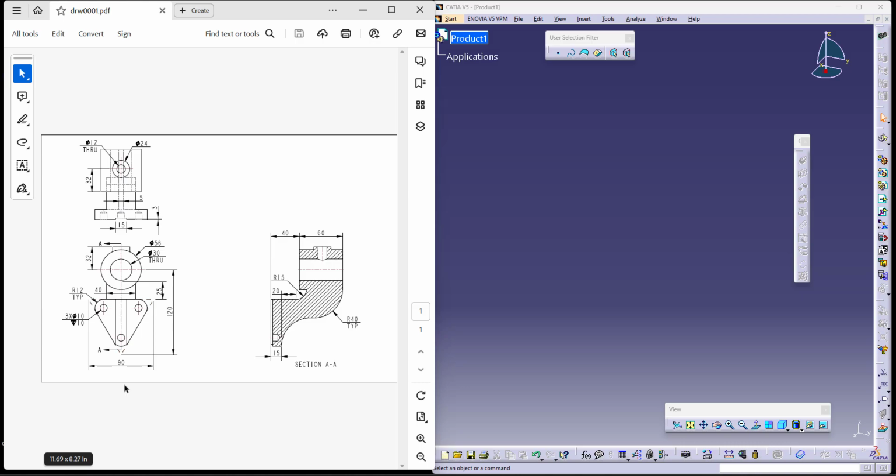Now, the first thing we do whenever we make a video is to analyze what angle of projection the drawing is in. This is actually in third angle projection with three views: the front view, the right view, and the top view. This is a very simple part component. You can decide on what is your 0, and you can start working on it.